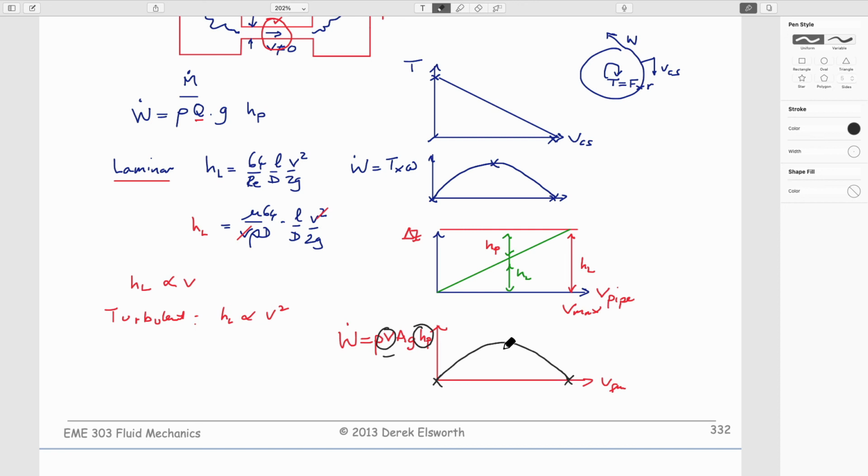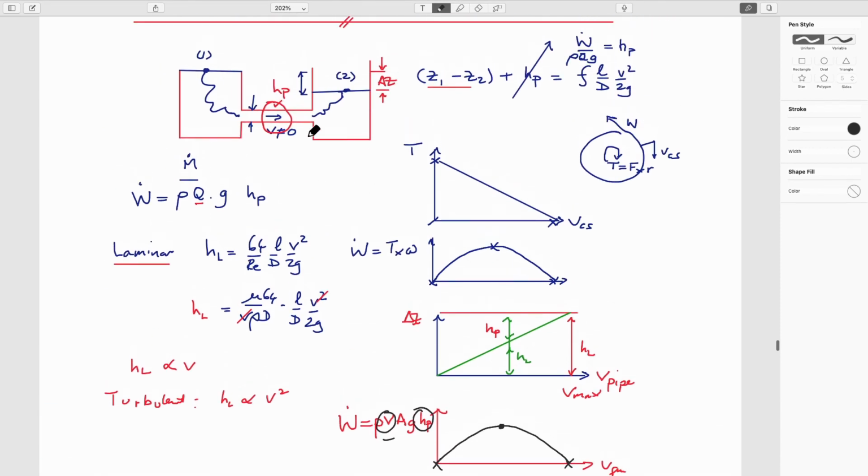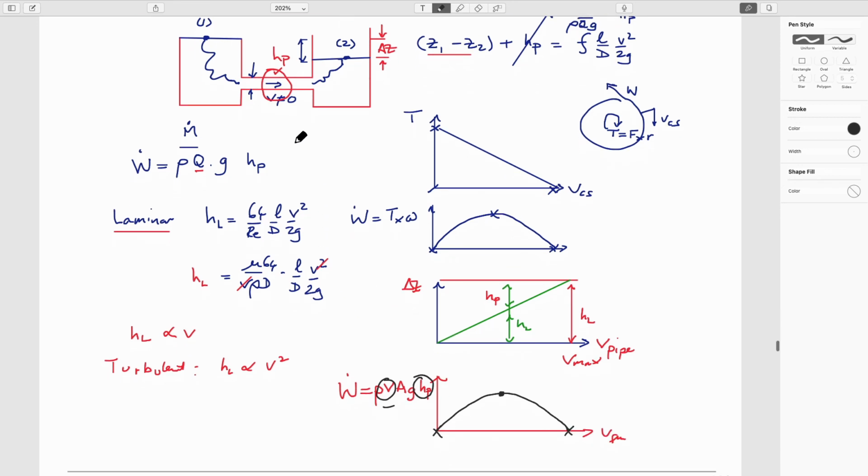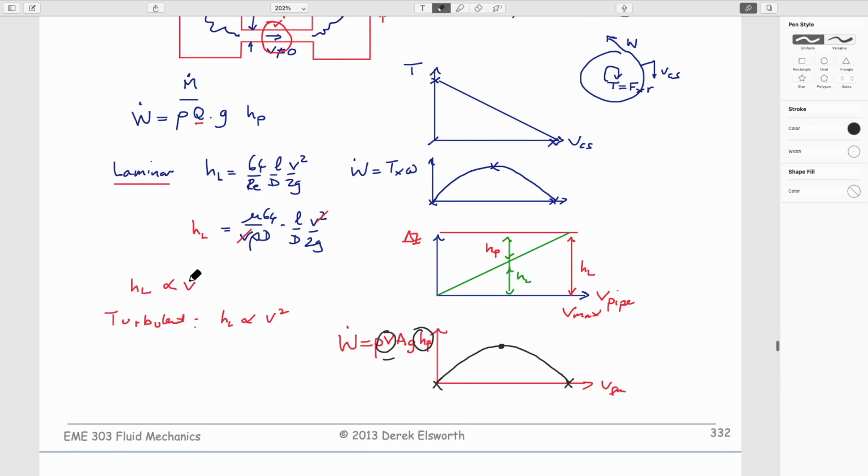In terms of understanding exactly how systems work, it's exactly the same as the sprinkler. Hold it static, force is a maximum, velocity is zero, no useful work. Let it run, but don't couple it to a motor, then you get the maximum velocity, but again, no work. These systems have a natural equilibrium velocity, and you change that velocity by putting something in the middle, it could be a turbine, it could be a mill wheel being pushed around, same deal, some mechanism by which you convert velocity into rotational energy and attach that to an electric motor, then this is the behavior. Okay, so that's it.